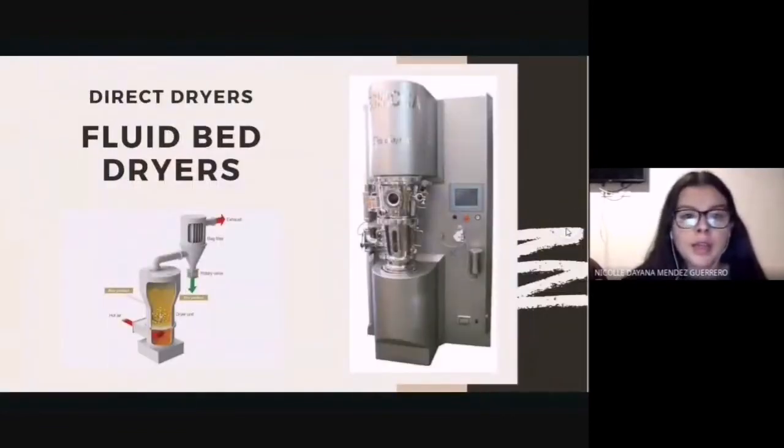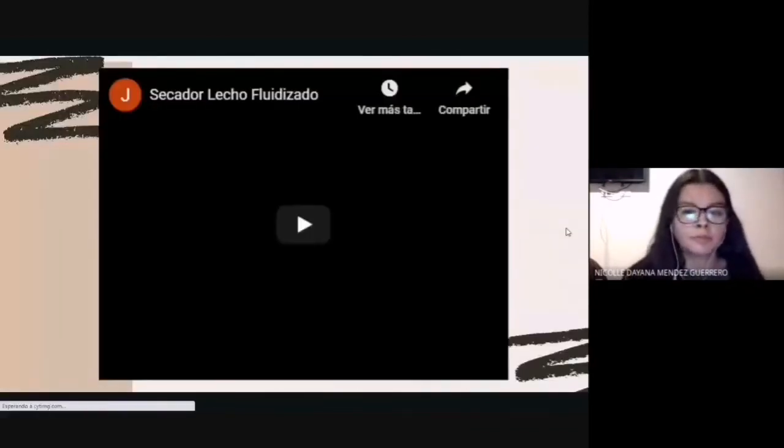Fluid bed dryers are widely used in the pharmaceutical industry due to their high efficiency in drying the granules obtained by wet granulation. Drying of the granules is carried out by the combination of the diffusion of moisture from the solid, mediated by hot air, and the removal of this moisture by forced convection. In this unit operation, the granules must be uniformly fluidized by hot air and designed so that efficient mass and energy transfer take place.